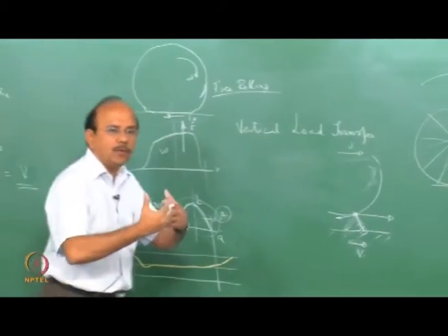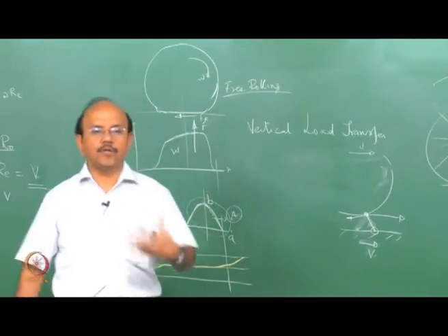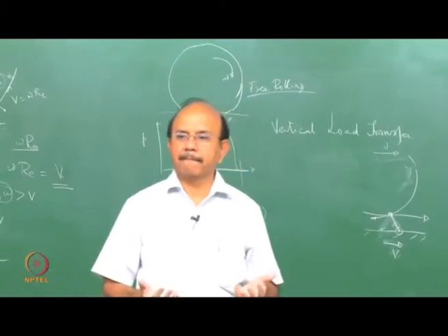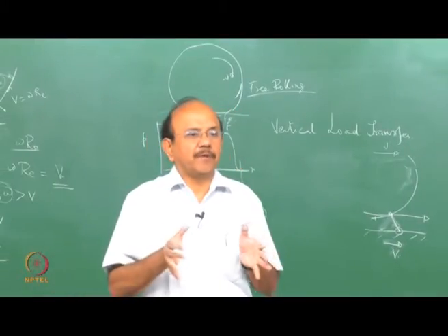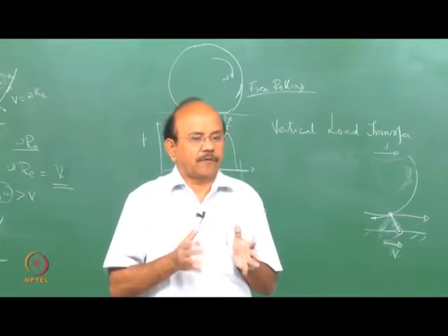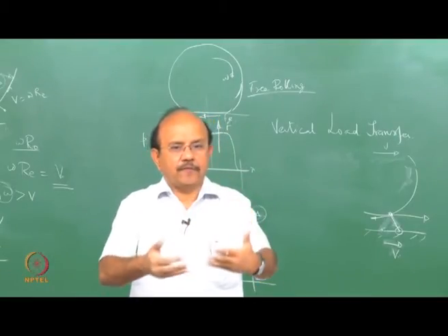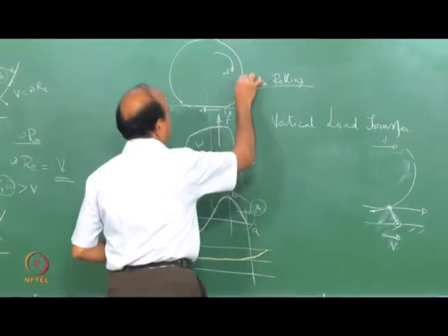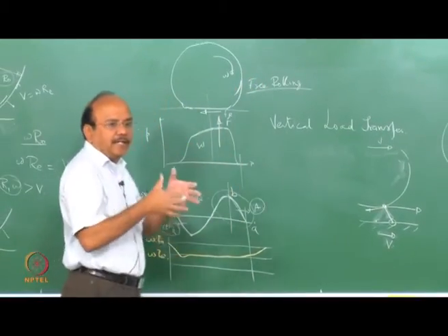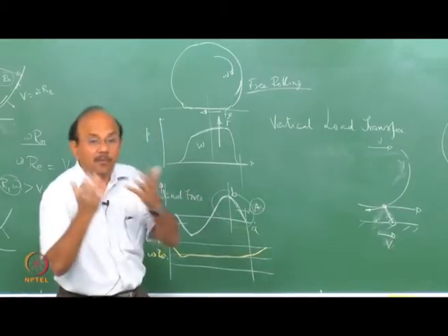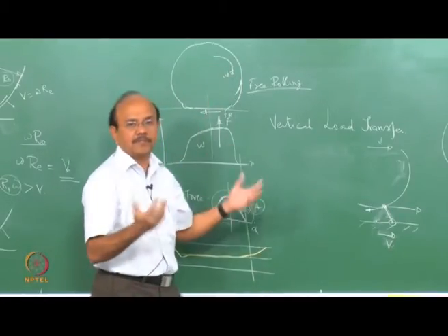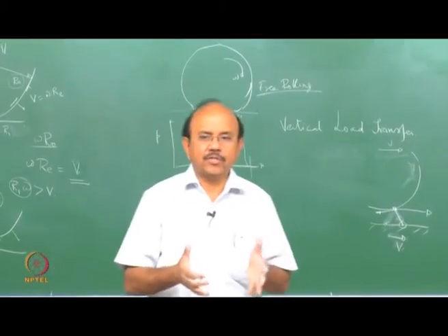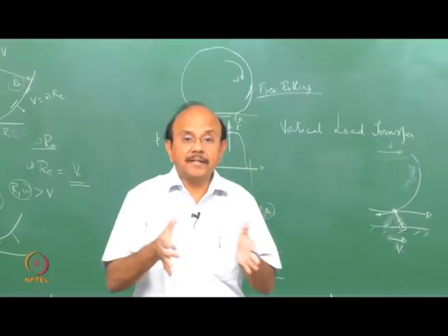As I roll, and as I come to the contact patch, the radius is going to decrease and I'm going to get compressed, because after all, I am in a free or stress-free state. I'm just lying there. As I enter the contact patch, I am a part of this circumference, obviously. So as I enter the contact patch, my radius is going to change, so I will get compressed.